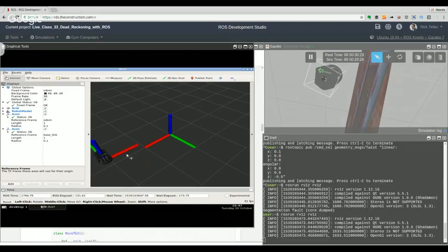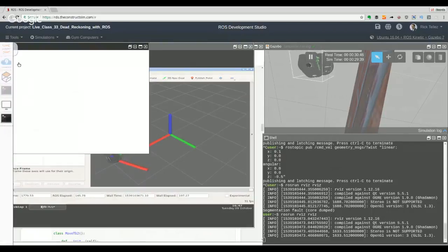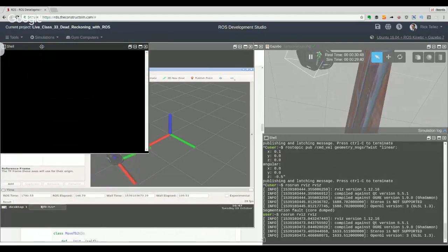And how can we see how much distance it is indicating? Well, let's go to the odometry topic. Yes, there is an odometry topic there that is being published by the robot, which is computing all the time the odometry of the robot. And for that, let's just go and listen to the topic. For that, we need to open another shell in Tools. And in this shell, we are going to do an echo of the odometry topic.